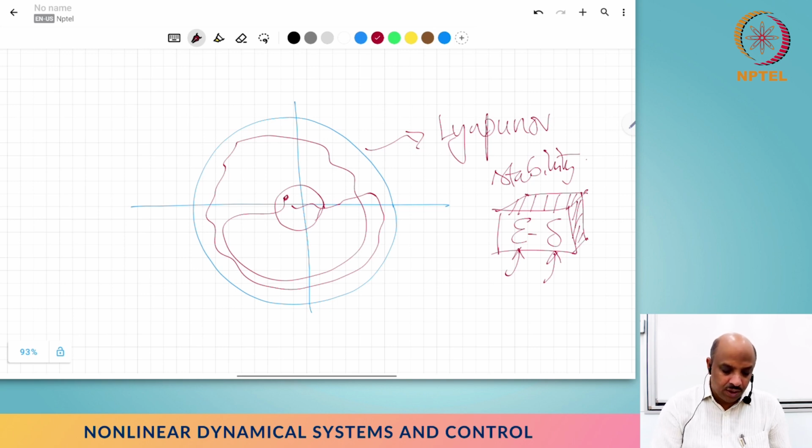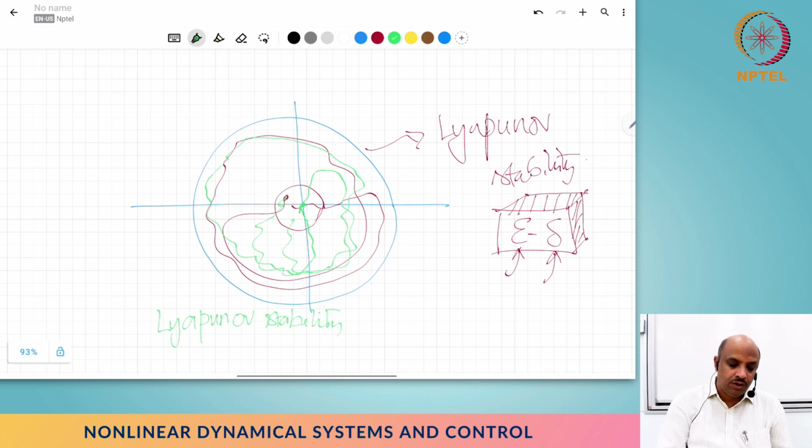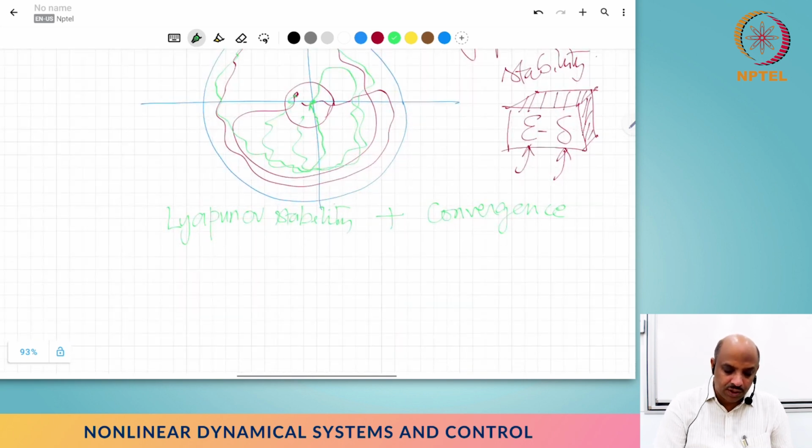But once we have Lyapunov stability, let's say I start here and then I may roam around, and then can I actually get back to the equilibrium point? Wherever I start, perhaps I may roam and never stay bounded within my original neighborhood, and then I can reach the equilibrium point. The difference between boundedness and Lyapunov stability is that you can actually demand the neighborhood in which you have to live, and that's the Lyapunov stability. But if we add convergence, if all the solutions are converging to a particular equilibrium point, along with this additional behavior of stability, we call that asymptotic stability.